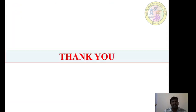Dear friends, so far we discussed the different efficiencies which are available related to the compression as well as the expansion process of a particular turbine system, or a particular turbo machine system where the fluid is very light in nature, like air. There we can have the pure expansion as well as the pure compression process. Under that situation, we can define the meaning of a static state and the meaning of a stagnation state.